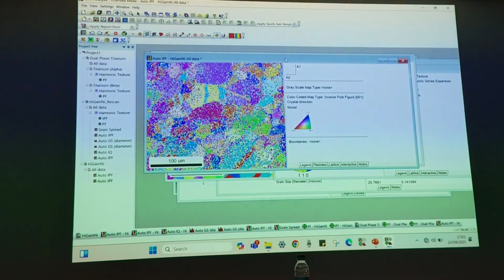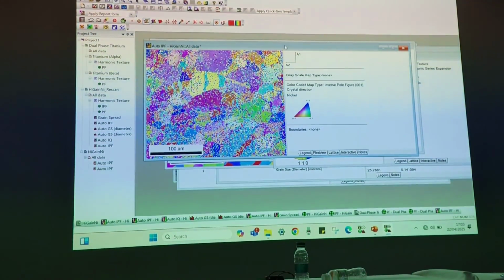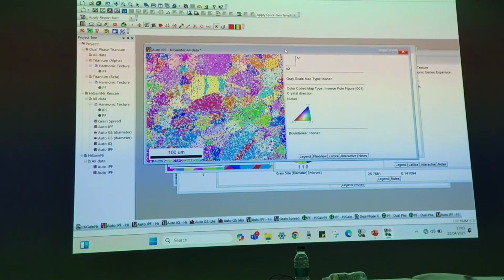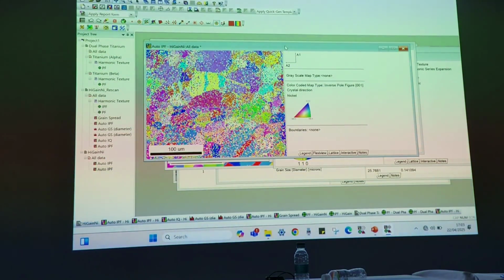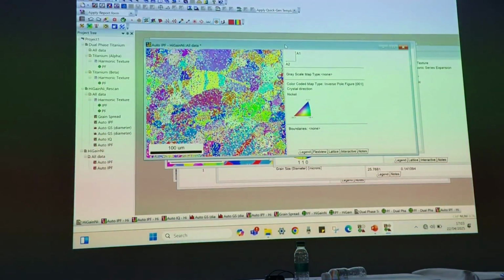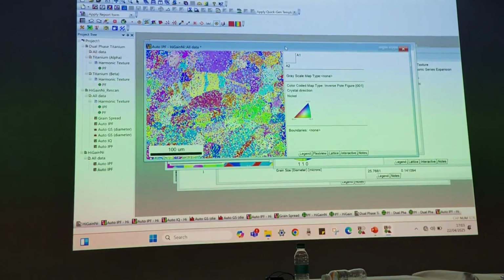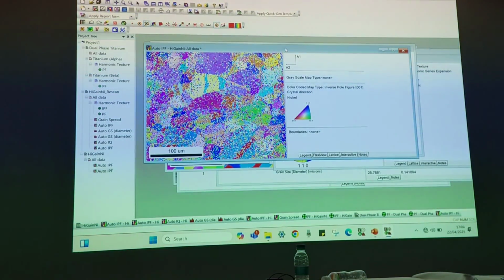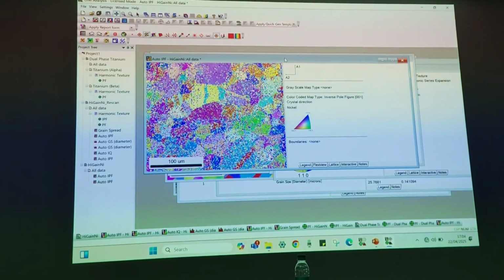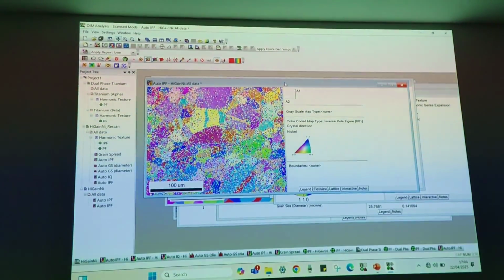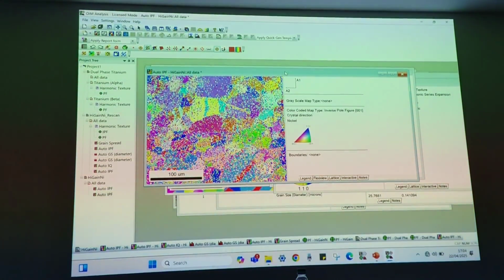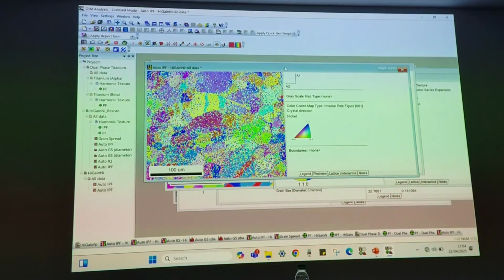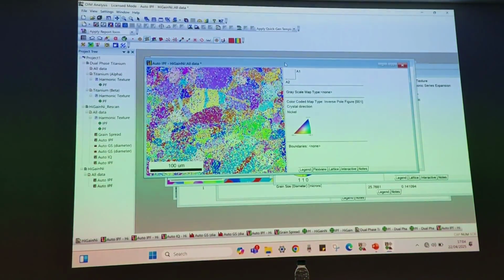For that, you need to have a goniometer which you can adopt for this. Because normal XRD, the Bragg-Brentano geometry, will support only theta to theta measurement. For bulk texture, you need to have a texture goniometer. So your sample will be moved through all 360 degrees, 0 to 360 degrees, and side rotation also will be there. So for that, you need a dedicated XRD system to measure bulk texture. But again, you can try to correlate both the results, bulk texture from XRD as well as micro texture from EBSD. Both results you can try to correlate. But for that, it needs to be done through XRD.